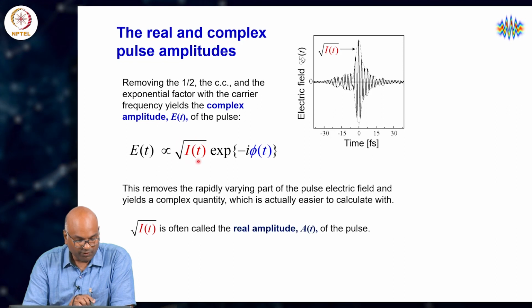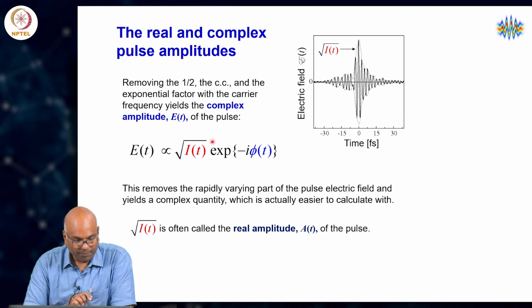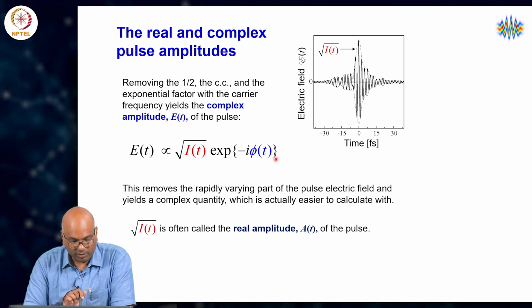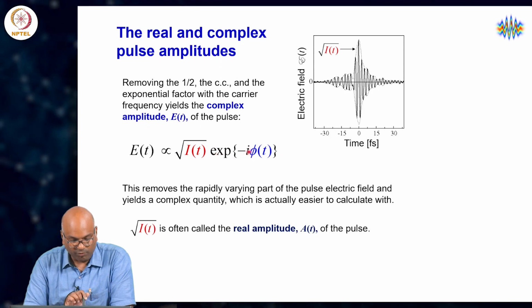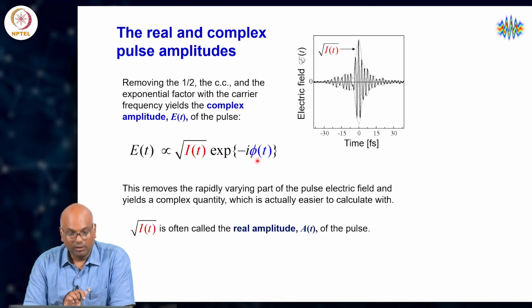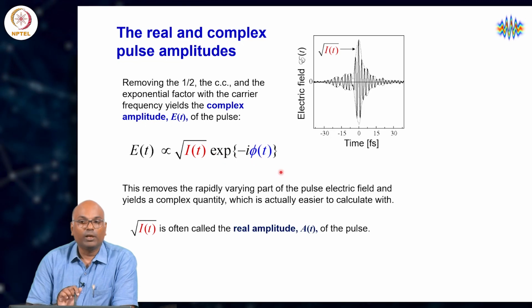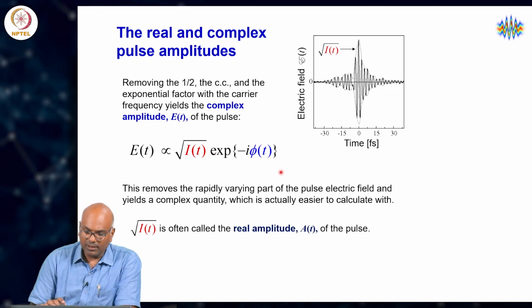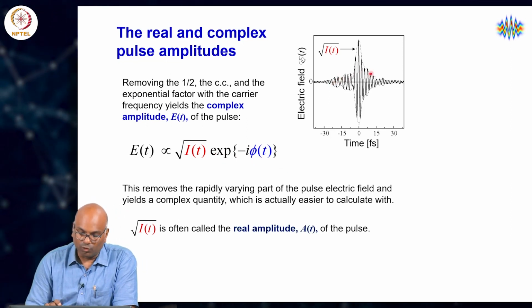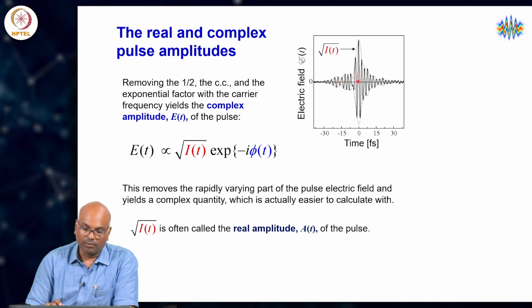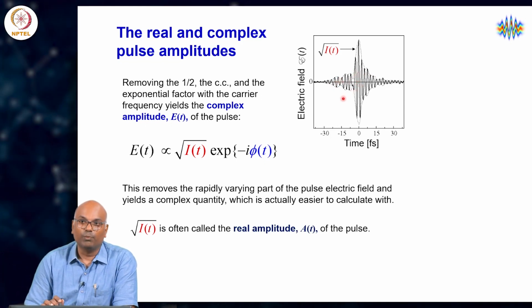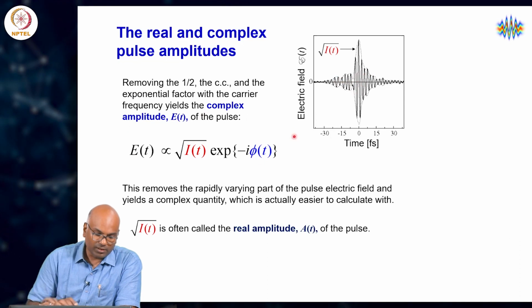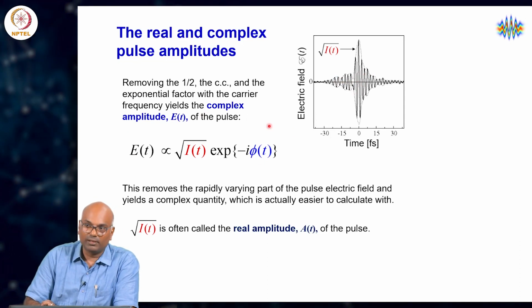But once you define the envelope, which is a real quantity, we here have the rest of the phase term, which is exponent of minus i phi of t, and we can see that the omega naught t term is conspicuous by absence. So that means the carrier is no more something we bother about. The carrier frequency is just a number, we bookkeep it, and for the rest we have the so-called complex amplitude.